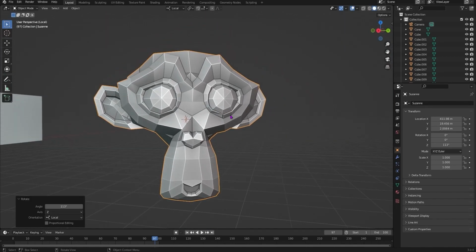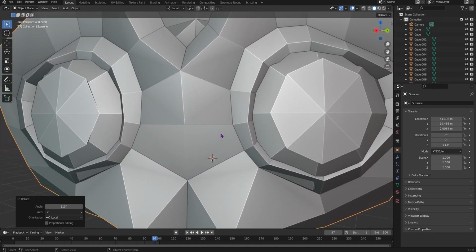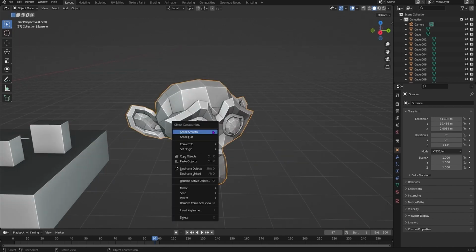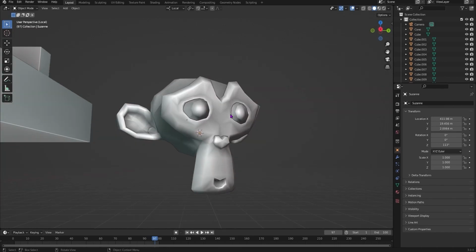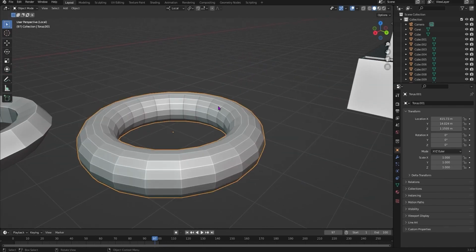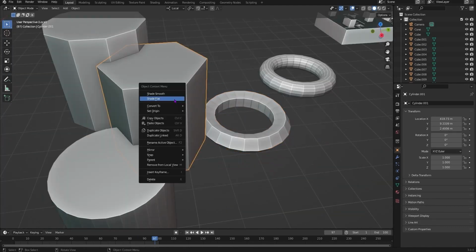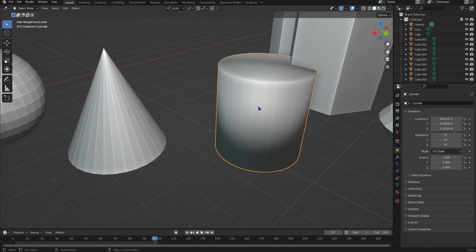So there are two types of shading in Blender: flat shading and smooth shading, and they both do about what you would expect. This can be important when creating something like a character. Not every one of our characters is going to be geometric and boxy. So you want to use smooth shading whenever you're trying to create something like a curve and you don't want to use a lot of geometry. That would be very expensive. Sometimes we see errors in the shading where there are hard areas that still need to be defined, like the edges around squares and cylinders just sort of get blended over when we go into smooth mode.